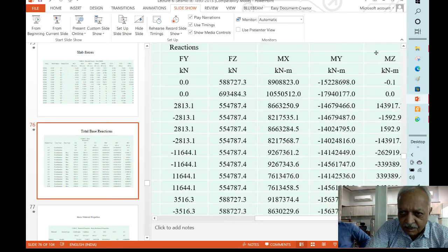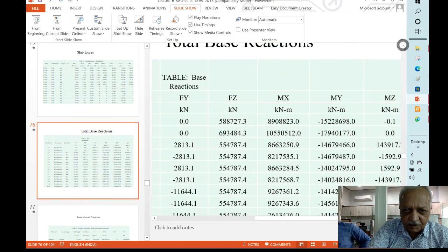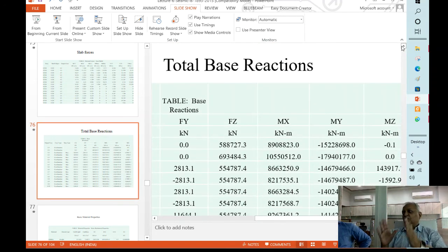Likewise you can consider the base reactions, okay, total base reaction, total load that you are applying on the buildings. It is sometimes a parameter, and an experienced engineer will roughly calculate per square meter how much load you have applied, and then he will come to a conclusion, whether it is reasonable, or whether some gross mistake has occurred, something like that. So on an overall grand scale, whether any mistake has occurred, conclusions can be drawn considering this total reaction. Individually whether a reaction is large or small, that is very difficult to decide.